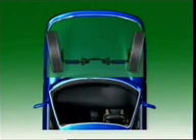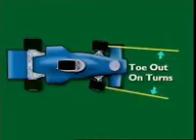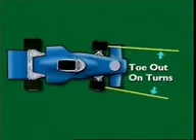This section examines toe in and toe out. When the front of the wheels, as seen from above, are closer together than the rear of the wheels, it is called toe in. The opposite arrangement is called toe out. The static toe setting is designed to compensate for slight wear in steering connections, which may cause the wheels to splay outwards or inwards. This means the wheels will be parallel when the vehicle is in motion, which avoids tyre scrub.